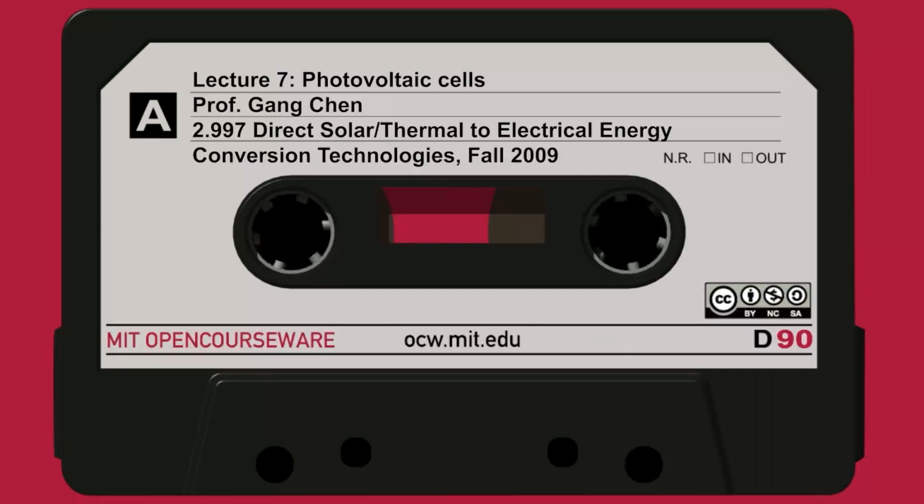Thin film. Here, say, the earliest one is the monosilicon crystal. With monosilicon, as we showed before, absorption is pretty good, so you can use it thin. But with amorphous material, the electron is very hard to move. There is a lot of dangling bond recombination. So you have to use really thin layers. The amorphous silicon cell is about 200 nanometers. If you can reduce that even thinner, it's probably better. Too thin, manufacturing is a problem. Your pinholes, all those, they're always filled up.